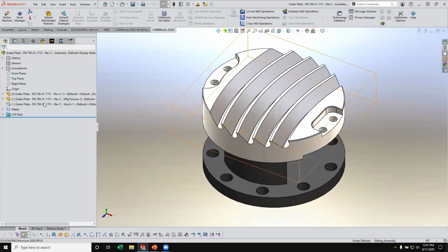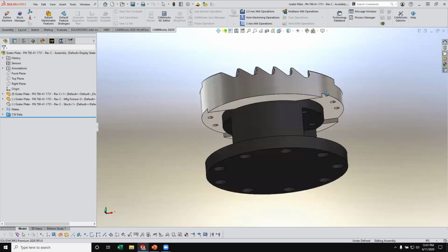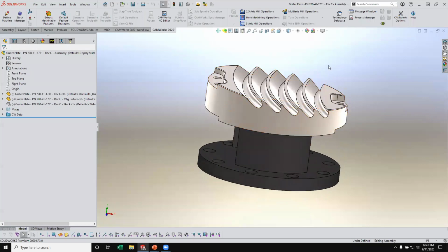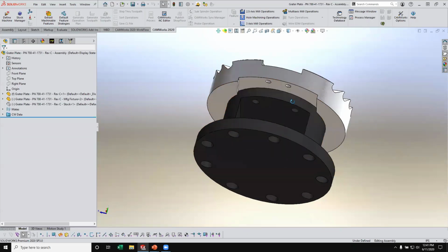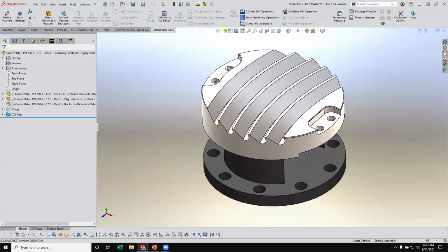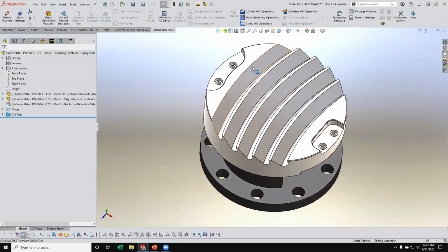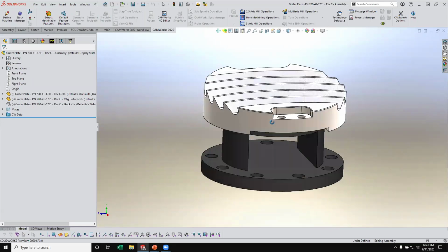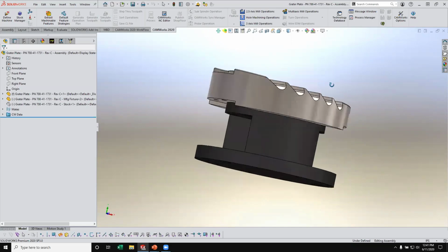And as you can see, I have an assembly here. I got my part, I have my stock, and then it's set up on this fixture plate. This has been turned down on the lathe to be round the size, and it's had this slot moved in the pre-op and the bolt hole so we can bolt it there, so we can set it up on this riser fixture, and then machine all these different channels in here on the 5-axis tombstone type machine. So that's kind of our goal here.